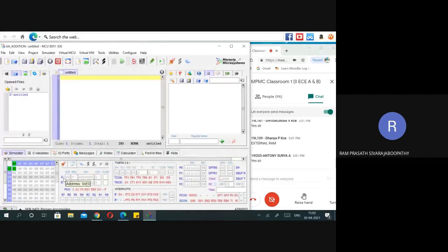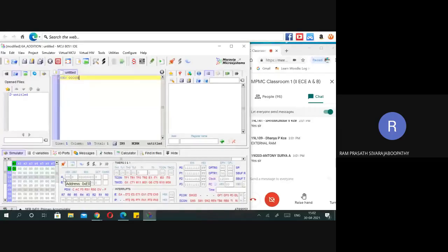So ORG 0000h, MOV DPTR, #8100h, MOVX A, @DPTR, then MOV B, A, then INC DPTR, then MOVX A, @DPTR, then ADD A, B, then INC DPTR, okay, then